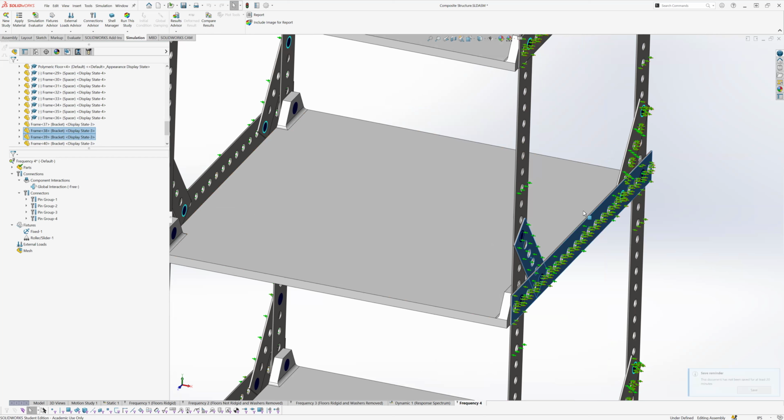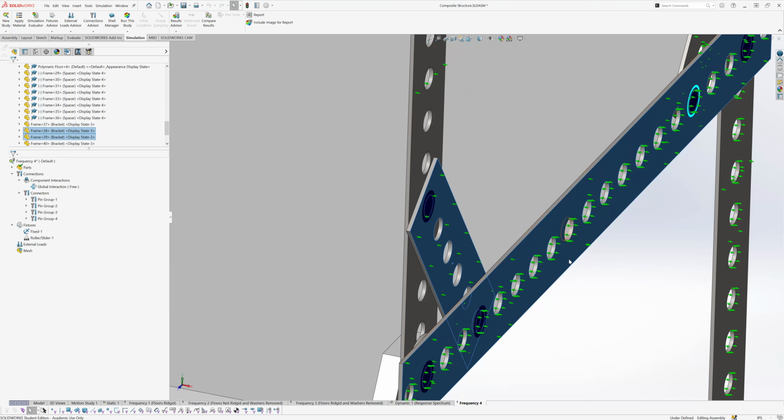If you remember, probably from a previous session when I was talking about Poisson's ratio, when you stretch a member, as it elongates, it'll get thinner in the other directions. By putting a roller slider on the inside as well, it's only really going to allow it to shrink in this direction here. It won't actually allow it to shrink here. Again, this is probably very, very minor for this specific study.